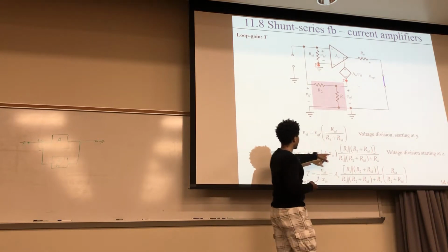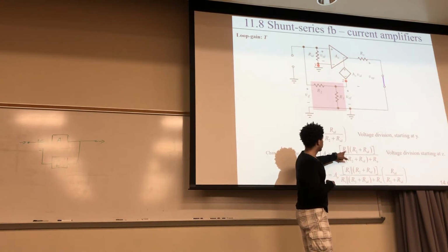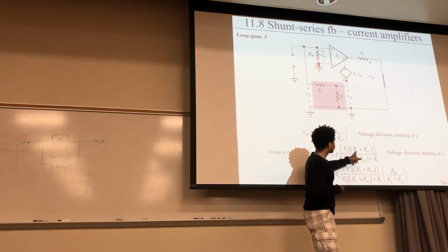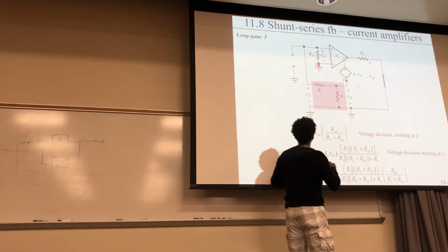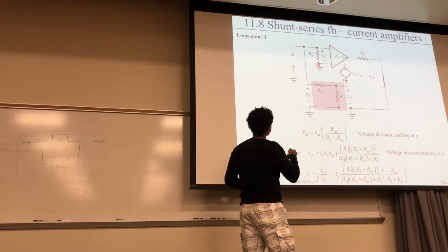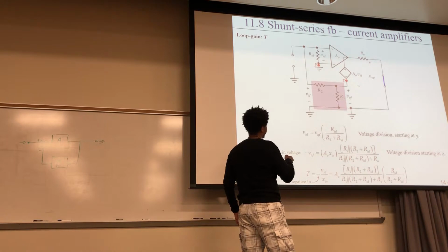And what you're doing, this time you're passing through R1, but that's in parallel with R2 and RID in series. So R2 and RID are in series right here, going to ground. And it's parallel with this one going to ground because they're starting off at the same node here, and they're both ending up on this ground node right here.